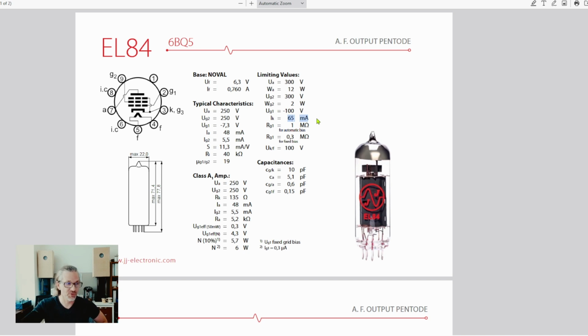And also because it was expecting that we only have 250 volts on the plate, it gave us like an 8-9 watt plate dissipation, but in this circuit, in the power supply, it miscalculated the output voltage of the power supply, and instead of the 12 watts, the plate is dissipating 15 watts. And now that's not good, because what is happening here is that we are exceeding 300 volts by 305, and we are exceeding the 12 watts by 15, and that's like a major thing.